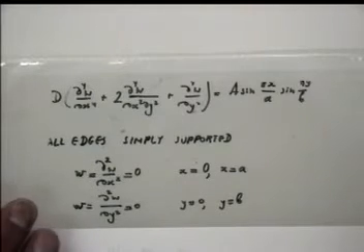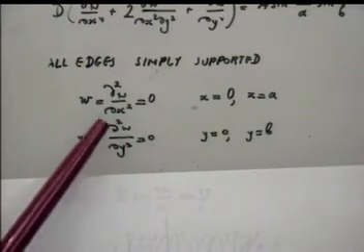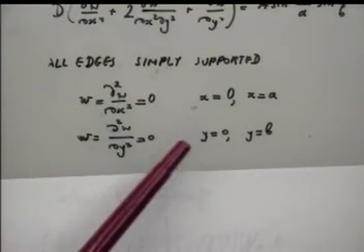Now, what are the boundary conditions? Imagine that they are, so to say, simply supported. What is simply supported? Like in the beam in this particular case, W equals d2W dx squared equals 0. That means the displacement equals 0 and the bending moment equals 0. Here in x direction, displacement equals 0; here, bending moment in y direction equals 0.